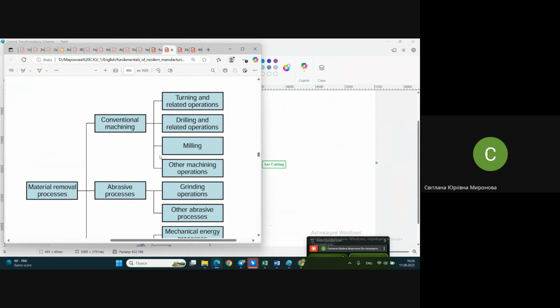And these thousands of grains, which are actually tiny blades combined with binder, may be made in the view of a tool. It may be a cylinder, a disc, flat, whatsoever. But the idea is the same. You are scratching material, you remove material by blades, either of big size or of tiny size, and simultaneously thousands of them work on the same surface.